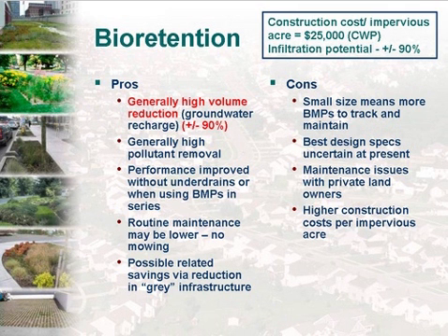For a bioretention, there's this high cost initially on a unit cost for the BMP itself, but the $25,000, or the $8,400 for a wet pond, doesn't consider land acquisition, long-term maintenance costs, or dredging costs for a dry pond over the longer term. So this bioretention cost is really going to seem quite small. Once again, $25,000 is a unit cost for treating an impervious acre, and these are designed for those smaller drainage areas, compared to a wet pond that is designed to treat much larger areas.